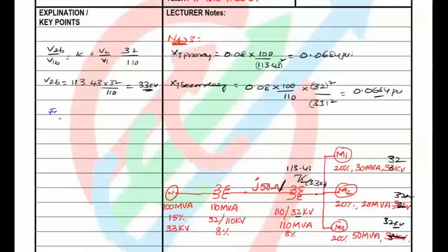So for the motors, the motor reactance XM1 is nothing but the per unit old value. So 20% means 0.2 into MVA new. The MVA new value is 100 MVA, and the old value here is 30, into kV old value over kV new. The kV old value is how much? Sorry, 32 here. So 32 whole square divided by 33 whole square.